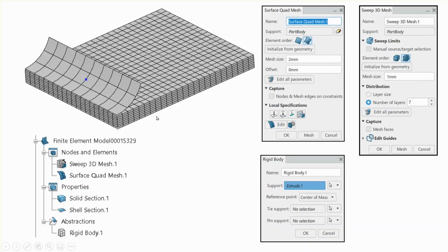The plate underneath is going to be meshed with solid elements like so, and the details of the meshing are done here. And I'm going to show you in a step-by-step way how to do this. And the cylinder is made of a portion of a cylinder. Actually, this is maybe about a 30-degree sector or something like that. So we don't have to model the whole cylinder.